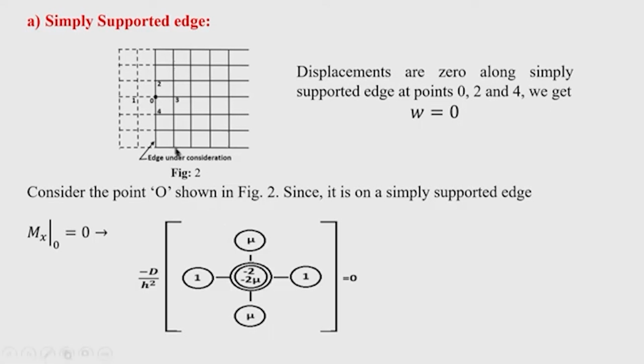So, if I place this stencil here, that means this center value is now placed at 0. Center value is placed at 0, very carefully note it. So, you get one value outside the plate. How to consider this? This is given by taking the imaginary nodes towards the left or towards the right, vertically or horizontally, and imaginary grids whose size is the same as this size.